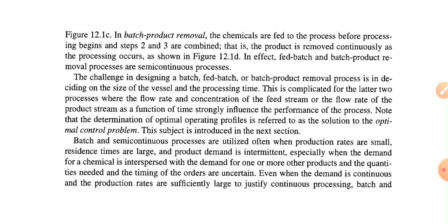Now, the challenge in the design of batch processes is deciding on the size of the vessel and the processing time, which is complicated. For the latter processes, the flow rate and concentration of the feed stream, or the flow rate of the product stream, as a function of time strongly influence the performance of the processes. Note that the determination of optimal operating profiles is referred to as the solution to optimal control problems. This subject is introduced in the next section.